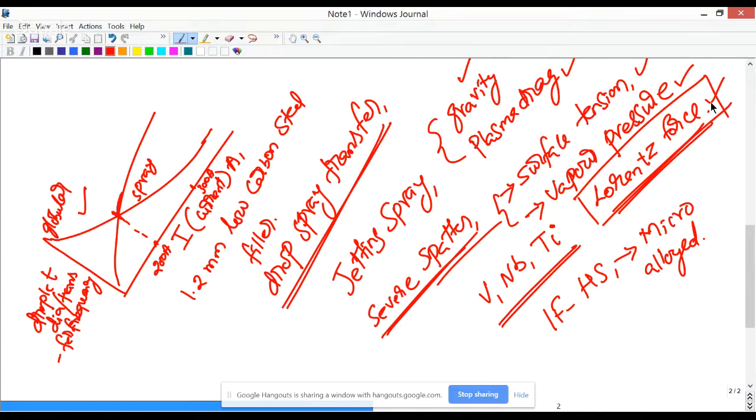Hot forming steels are deformed when the temperature is fully austenitic. So in order to avoid all the complexities in the intercritical region and to achieve a fully martensitic microstructure, we always aim to increase the temperature above the A3, the austenite completion temperature while heating. So we can achieve a 100% martensitic microstructure upon forming when you quench the formed component.